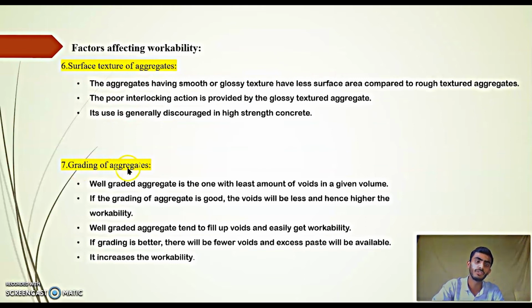The seventh is grading of aggregate. Well graded aggregate is one with the least amount of voids in the given volume. If the grading of aggregate is good, the voids will be less and hence the workability higher. This means that well graded aggregate should be used and the voids should be less. It will affect the workability.